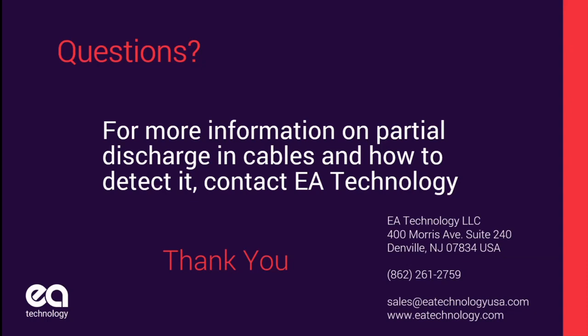We see about 25% of the time online that you get a big enough reflection to calculate the distance. When you do an offline test, you lift both ends of the cable, you have a very abrupt change in impedance, and that's what causes the reflection. When you're online, you have less of a difference in impedance, so you get a smaller reflection, plus you have a higher noise floor. So we see 25% or so of the PD we detect, you can actually determine the distance, but that's not the real goal.